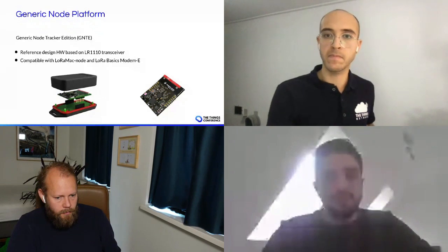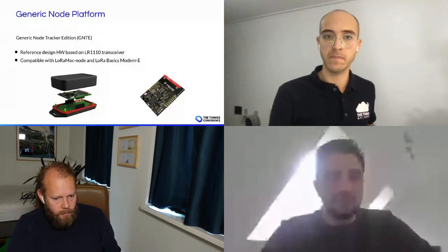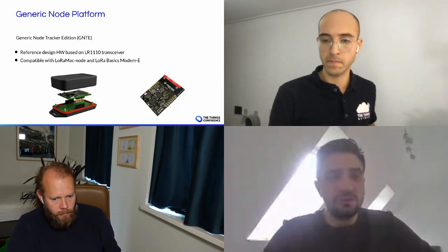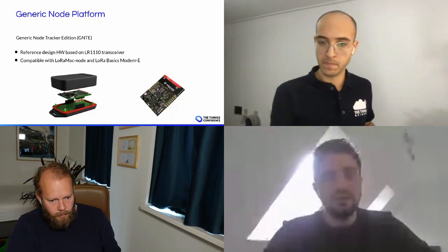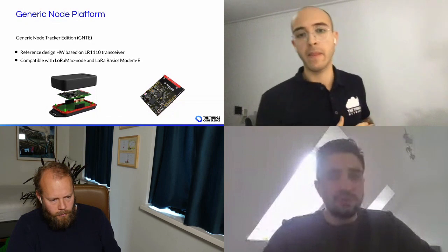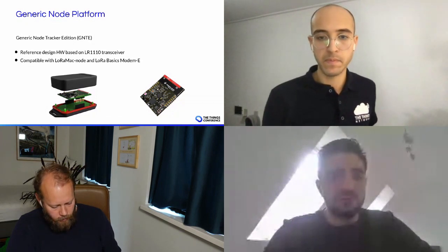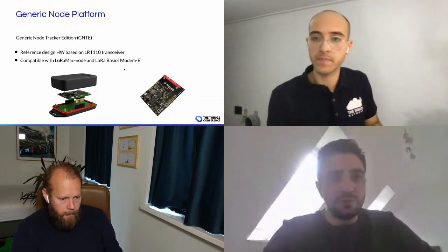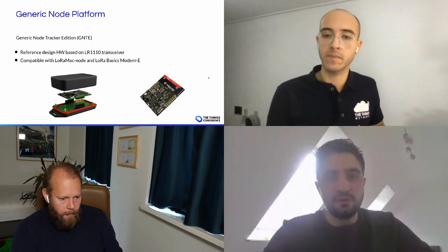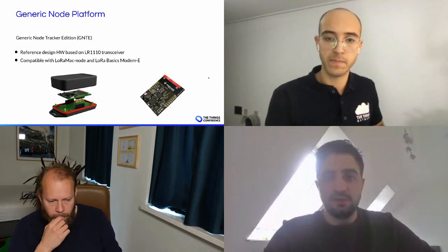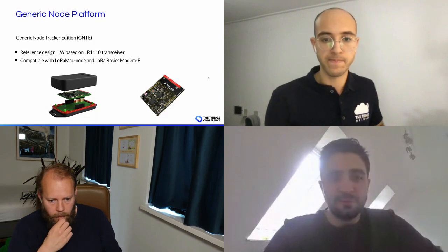And we are using one single antenna in a tri-band mode, and we are multiplexing it. That reduces the BOM cost and also reduces the device size, so that we don't have to use 3 different antennas for the 3 different frequency bands. Right now it's a very early prototype. We are working to verify the design, and later on we will also open up more design details.